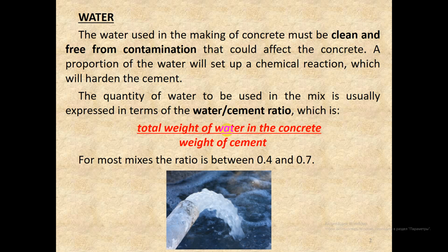For most mixes, the ratio is between 0.4 and 0.7. Usually, if water is drinkable, it will suffice for concrete, unless sweetened by sugar.